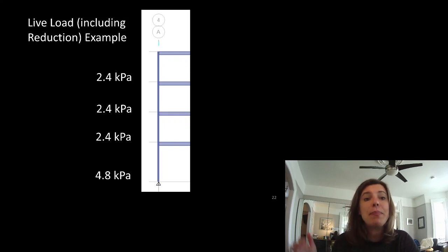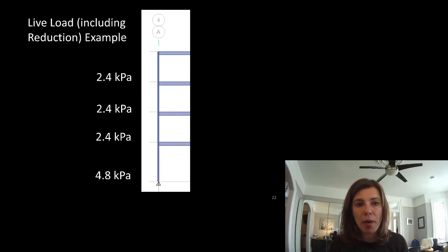If I tell you that people can get up on that roof, you might have a different live load requirement. But I would be very explicit if you had a different live load requirement on the roof that you need to design for. If you're doing a studio project that is accessible, so maybe it's a rooftop restaurant or a garden park, something like that, you will need probably 4.8 kPa. I doubt it's going to be an office up there. It would probably be an assembly area if you're having it up there.